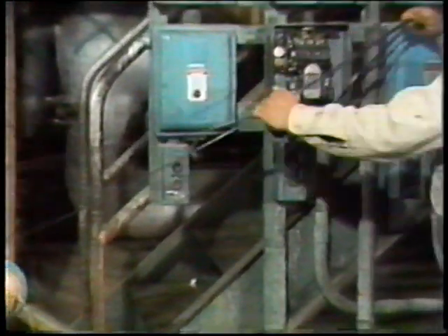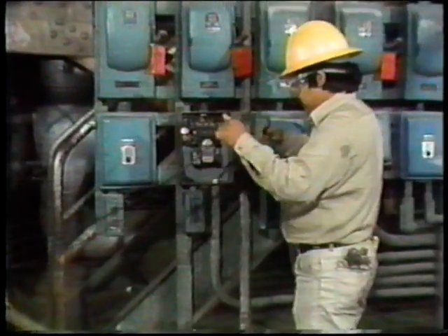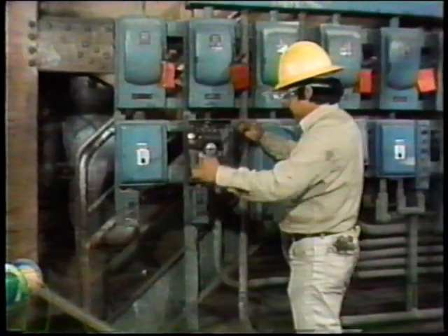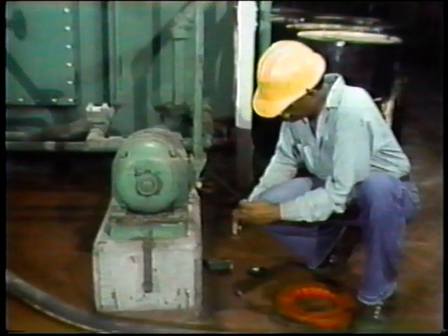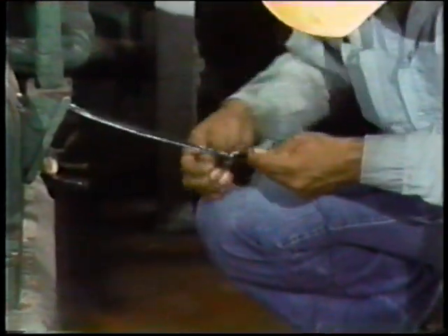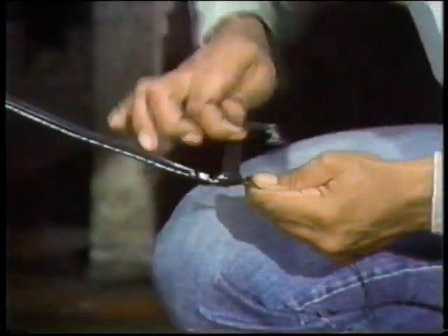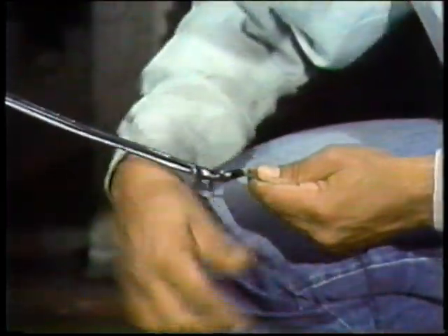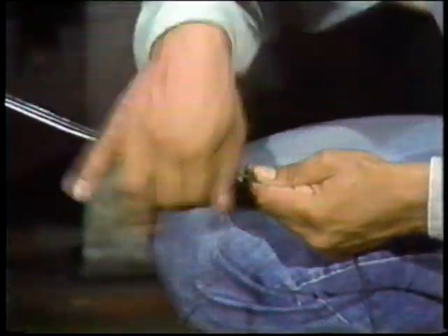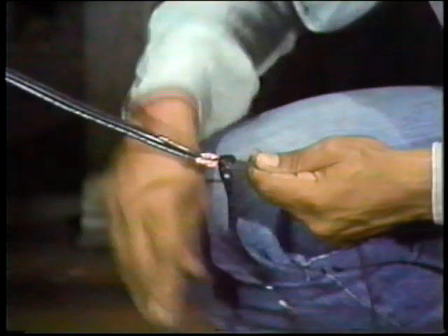This will keep the conductors from rubbing on the edge of the conduit, and it'll also help Bill as he pulls. It should be almost all the way through by now. Whenever you're pulling conductors through conduit, it's a good idea to leave a little extra length projecting from the conduit. Then, if for some reason you need an extra inch or two, you've got it. Okay, Bill's got what he needs. He unwraps the tape at the hook and straightens out his conductors. A little extra is left at this end, too.